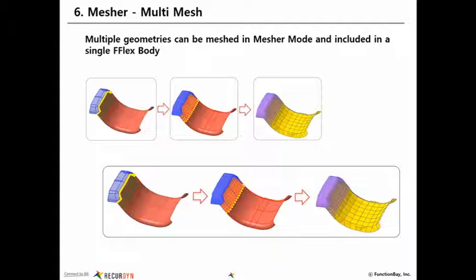And so in V9R2, I guess to back up a little bit, oftentimes when you import geometry from CAD, the way that it's imported actually contains multiple solid bodies in what's considered one body in RecurDyn.